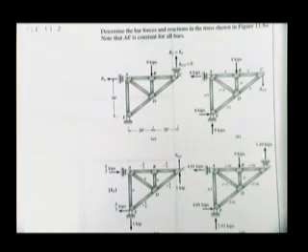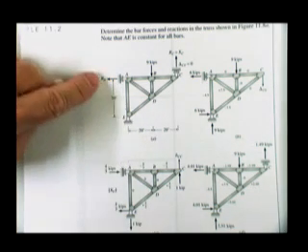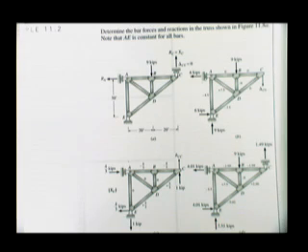All right. We've been doing mostly beams. Make sure you realize there's no difference between the beams and a truss. This truss is statically indeterminate. It would have been a beautiful truss had they simply pinned the bottom and put a roller on the top. It would have sat still just fine.